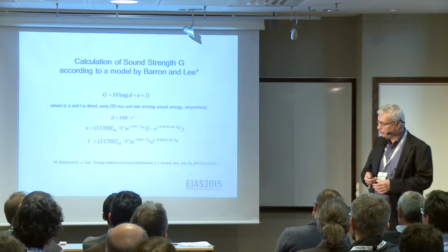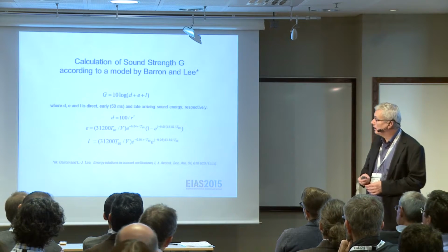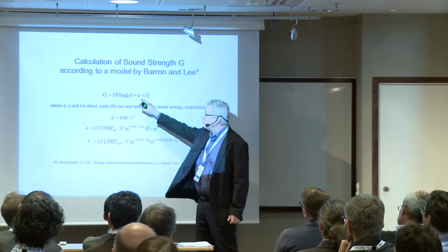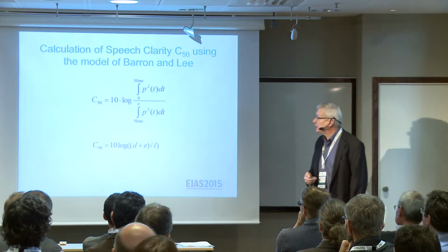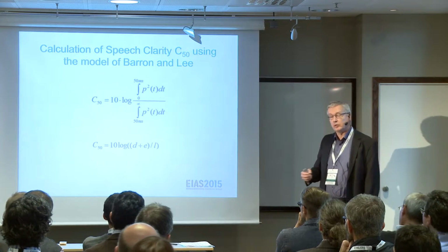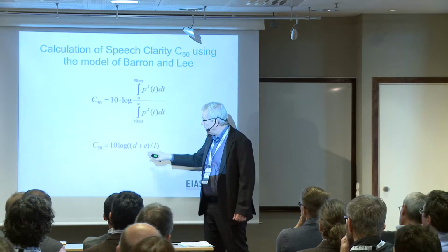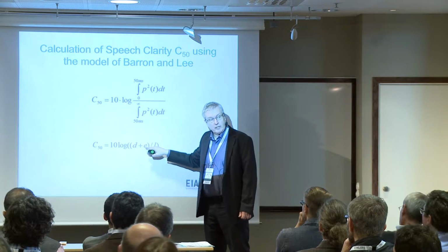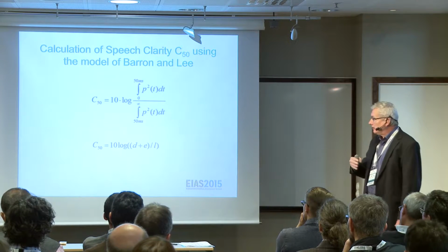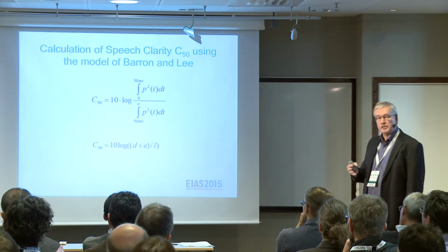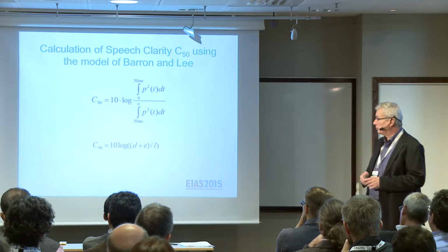I will also say that knowing the sound strengths here and knowing the energy of the early and late part, then it's quite simple to calculate the speech clarity, because that's simply a ratio between the early energy and the late one. So you simply have the factors here. And even if you change the time limit to some other values that we heard yesterday, 35 or whatever, 80, it's just to put in the formulas.